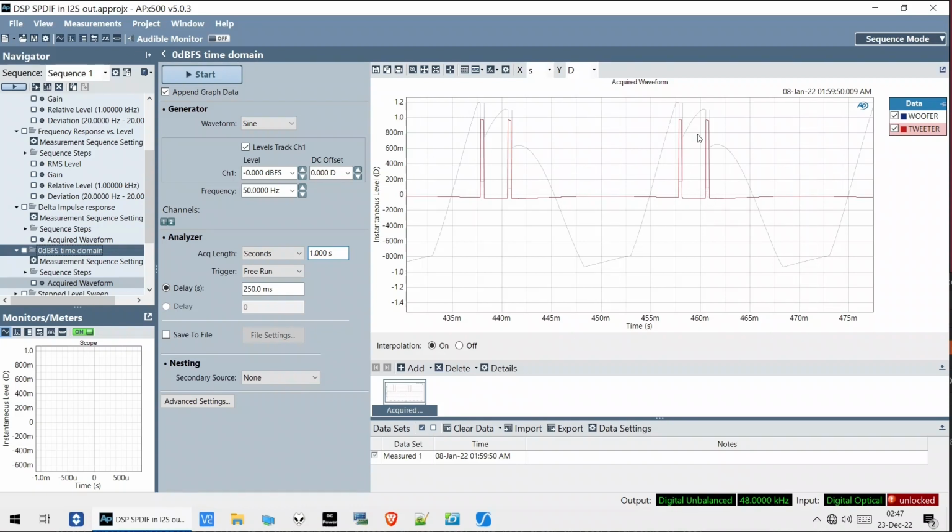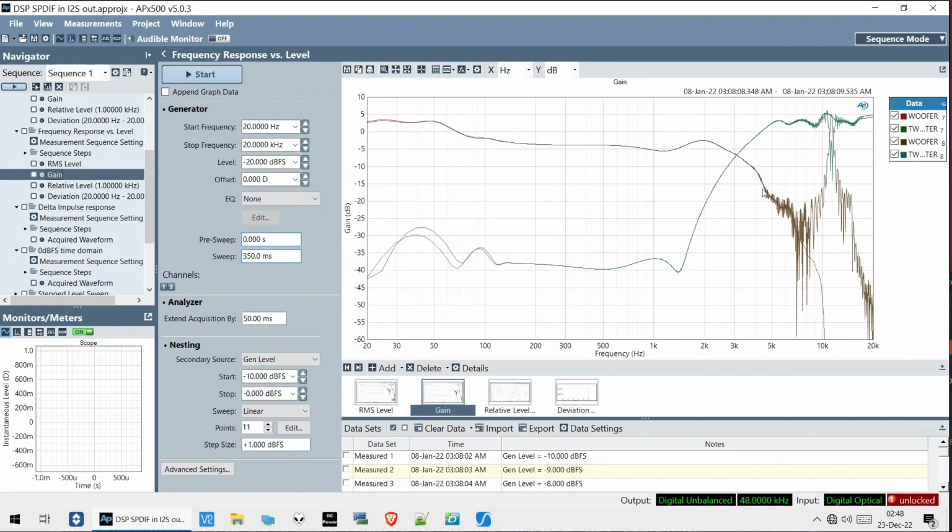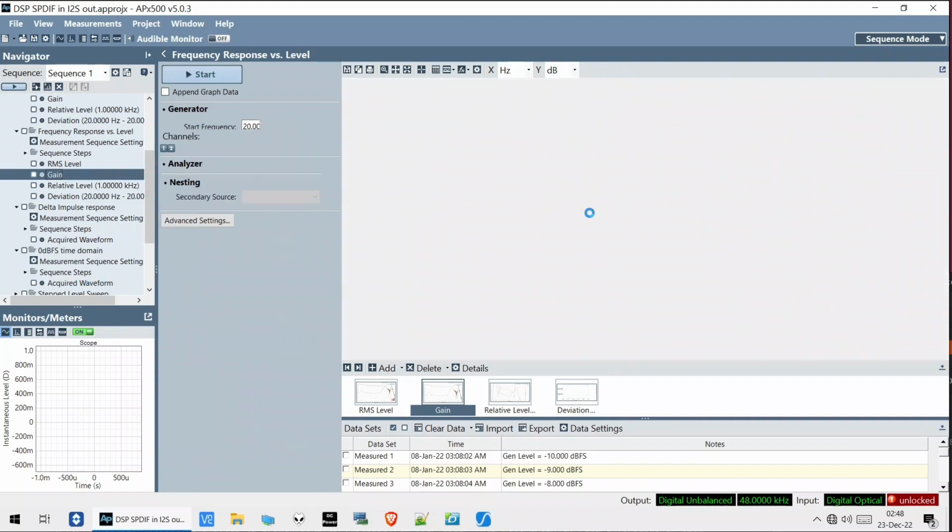But it does explain sort of the picture you saw here, that there are now very high frequency distortions in the woofer signal, even though it's trying to play something over here. It's actually trying to play 50 Hz here. But these quick pulses manifest in the frequency domain over here, and they also impact the tweeter signal. So this is just the worst thing you can have happen, actually.